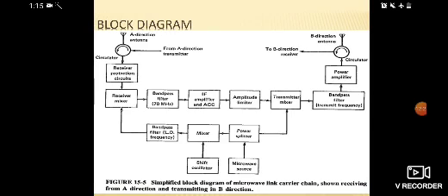But whenever we amplify these microwave frequencies, we require microwave amplifiers that are very costly and difficult to maintain. Therefore, the RF signals received from the antenna are down converted into the IF amplifier. I have already said that in our communication receiver systems, all of the receivers have IF amplifiers only, not other amplifiers. Why? Because it is very tough to process signals in the range of radio frequency or above. It is very difficult to process.